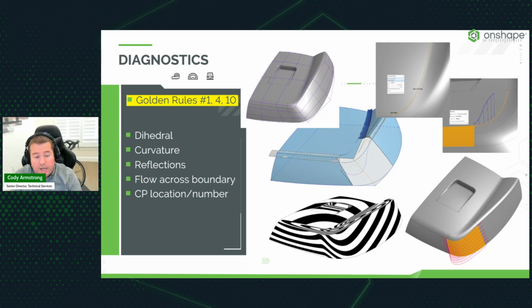And that's just parametric CAD in general. If you have a trimmed edge that has all these jagged definitions to it, and then you start to build a whole bunch of features off of that, and then later realize you have to trim or change that trimmed edge, you have a lot of cleanup work in redefining the parametric relationships between those subsequent features and the trimmed edge. And that applies to everything. If you don't have a smooth transition between the two faces, and then you build a dozen features on top of that face, and then you realize later on that it's not curvature continuous, or it has a sharp transition in an area where you weren't expecting, then you have a lot more work for yourself than if you had run the diagnostics, or viewed those problems before building subsequent features.